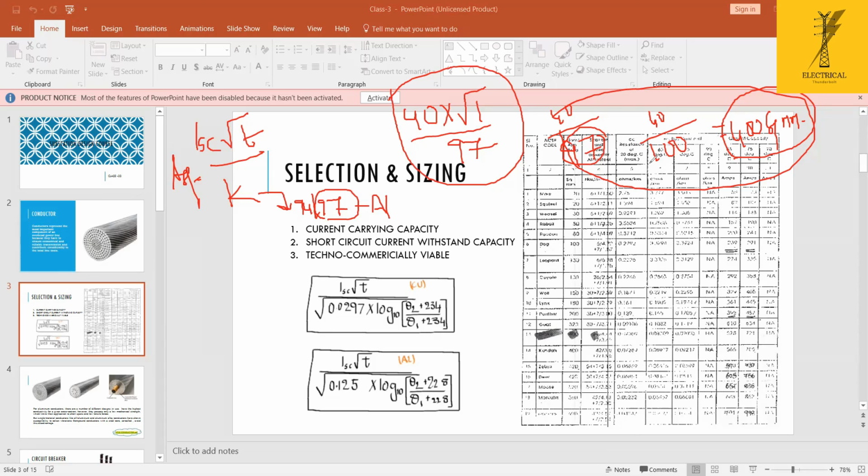Again, in a normal way, we have to do the transient analysis using software or whatever it may be. In practice, generally for 220 kV we will use the conductors Moose and Zebra, which I will discuss in the next one, and for 33 kV, Panther. So we have some standard conductors. We are using those standard conductors for specific voltage levels.